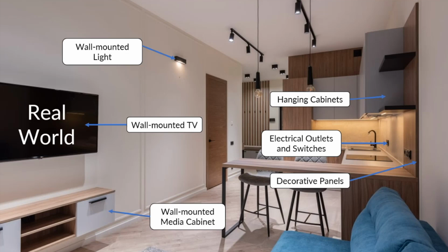And all of these things can affect the acoustical performance. Oftentimes, they're all sort of weaknesses in our assembly that can reduce its acoustical performance. So if the goal is to, in the real world, actually reduce the amount of sound that's transmitted from one space to the other, we've got to address all of these details, not just have some assembly that gets a particular STC rating.